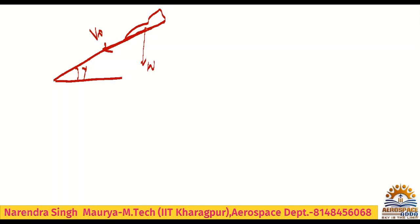This is gamma, so this will also be gamma. This component will be w cos gamma, and here the horizontal component w sin gamma. This is the velocity v, perpendicular to this will be lift, and opposite to this will be drag. Now you just equate the forces.